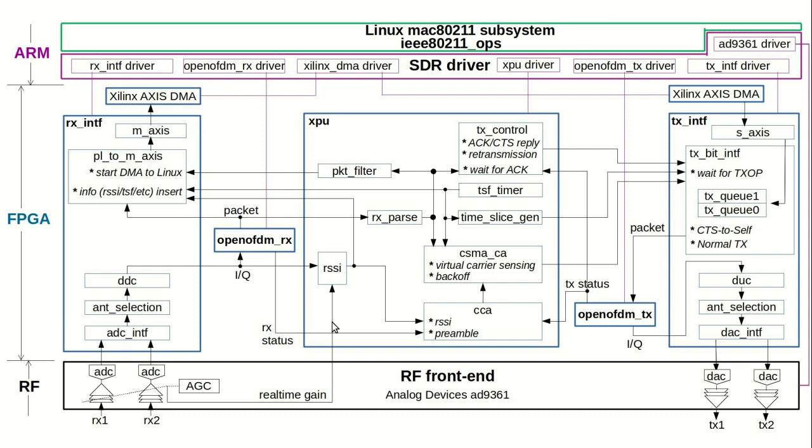And in the FPGA design, all the necessary building blocks of a Wi-Fi chip are there. You can find all the source code of these building blocks, such as the openwifi TX, that's the Wi-Fi transmitter. We have built the Verilog-based Wi-Fi transmitter according to the Wi-Fi standard. You can find all the details here. That's the physical layer part. Receive packet, generate IQ sample.